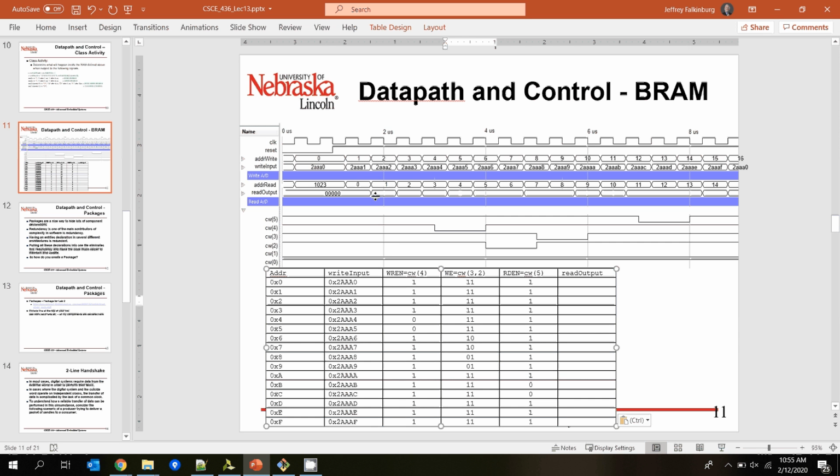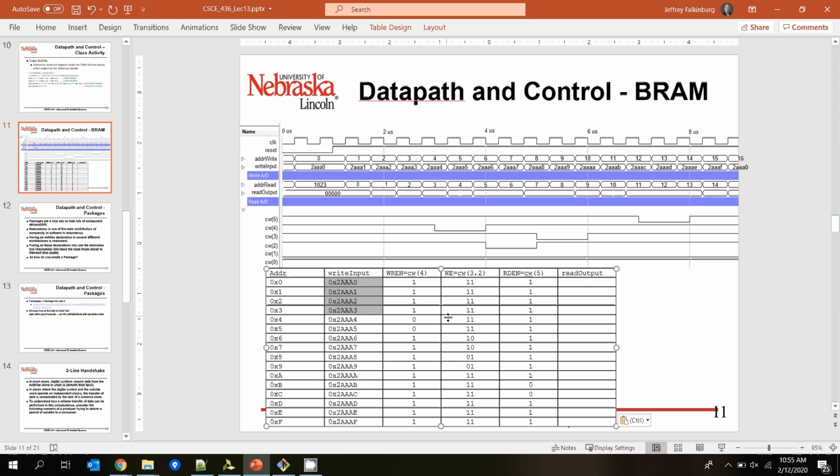So as we step through this and go line by line, the value that's going to get written and then read. So write enable, we're going to write these values into address 0. So we're adding these 4, they're going to be put into memory, and those values will get read on the output. When we look at it in the waveform, we write address 0 here, and on the next clock edge, that's when the read address is set to 0. So then after that clock edge, we're going to actually read that first value out.